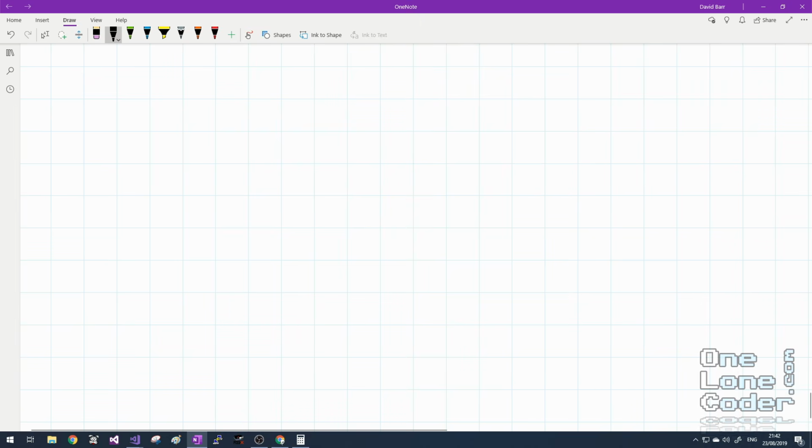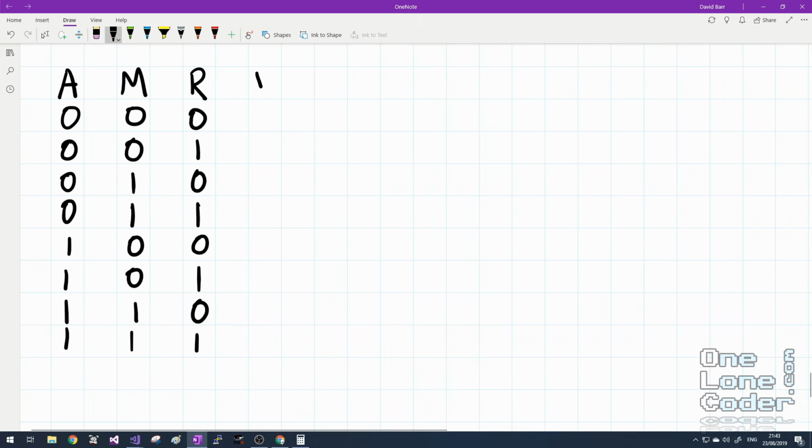We can compute this with bitwise operations. So I'm going to build up a small truth table. I'm going to take the value in my accumulator, the value of the data that I'm adding, I'm going to assume the carry bit is 0 just to keep this sensible, and also the result. And what I'm going to look at is the most significant bit for each of these bytes. I'm going to create an additional column which is whether the overflow bit should be set.